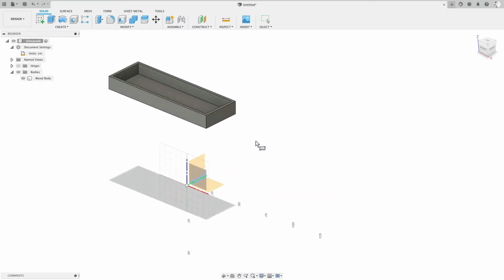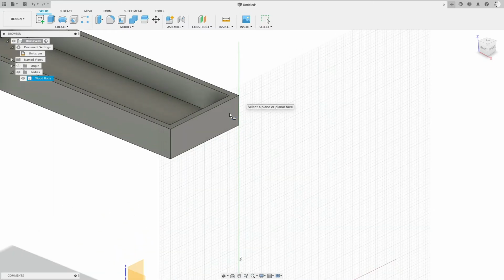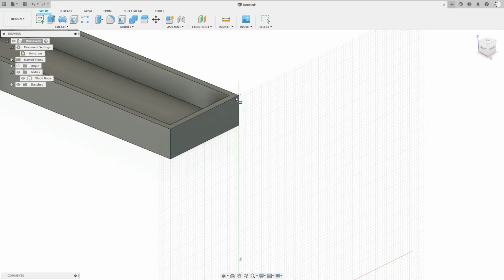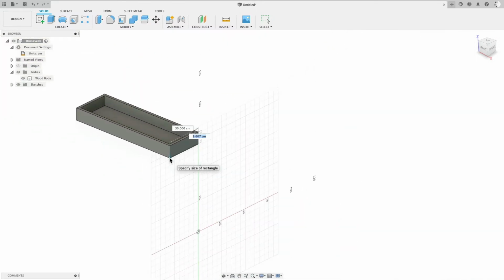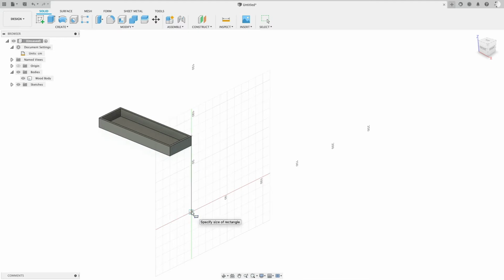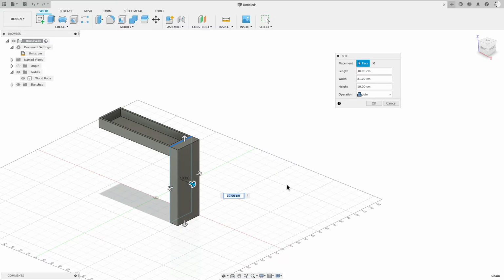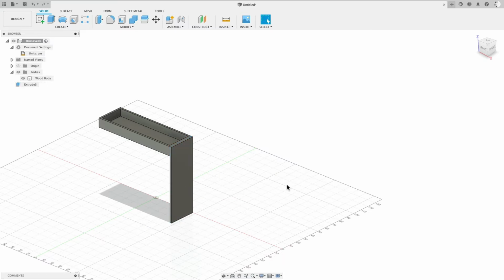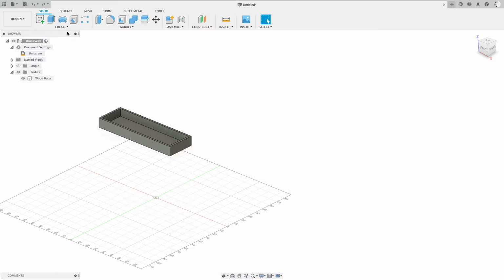So we can actually start drawing on this base or somewhere here on the ground. Since it actually should be connected here, it will make sense to draw on this face. So on this grid, click, and then now I can go to here, click, go to there, and then go down. Go to here, and you see it memorizes the snap point for a moment. And I had this memorized. And you see very easily it finds the left position and the height. Click, and this should be 2 centimeters. Very good.